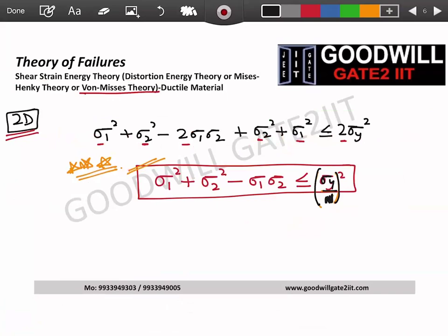I hope this factor of safety thing is clear to every one of you. Now, we have the formula, we have the name. Now comes what is the ratio. Again, we can perform a torsion test, but all these people have already done that. If you apply a torsion test, the relation between tau y by sigma y is basically 1 divided by root 3.